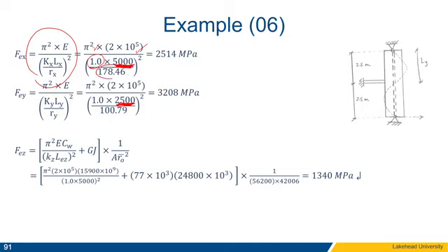And we will use the radius of gyration that we just evaluated for the combined section and crunch those numbers together to get the FEX value. Exactly similarly for the FEY, everything is identical except for the buckling length and the RY. And you will get yourself the new FEY. Okay?